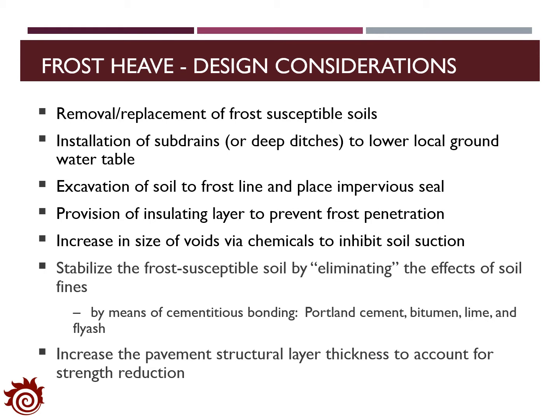In our previous lecture, we analyzed the impact of the frost heave on pavement design. And from the analysis, we found that frost heave could actually reduce the strength of the pavement. So in the design of the subgrade structure, we have to put the points listed in this page into consideration. First, if there are some frost susceptible soils on the ground, we need to think about removing them and replacing them with some other materials.